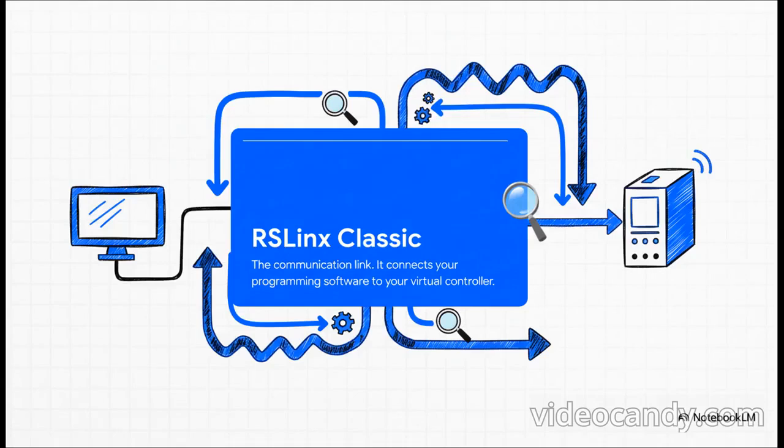Next, we've got RSLinx Classic. You can think of this as the universal translator or the communications hub. Its entire job is to build a bridge so your programming software can talk to your virtual PLC. Without RSLinx, they wouldn't even know the other exists. It is the absolute critical link in this whole chain.